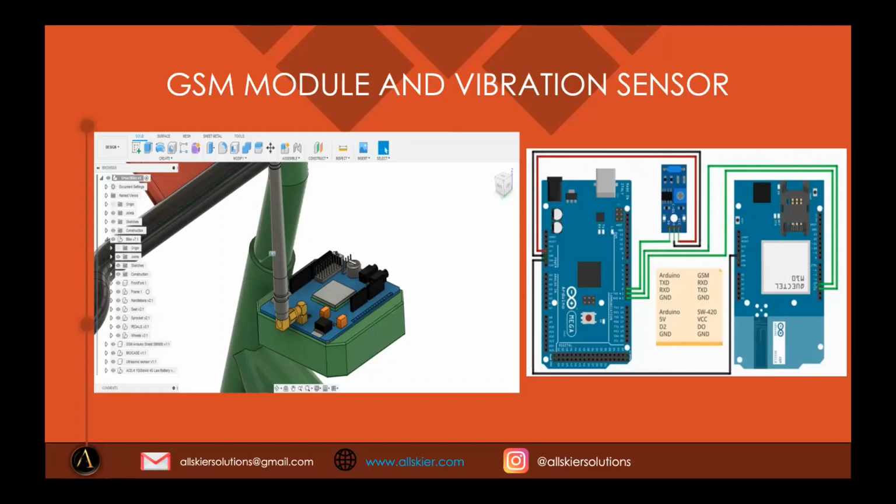Well, the microcontroller unit has an inbuilt op-amp, and it is able to amplify the signal. Well, what is the point of this op-amp? It has a preset value. So whenever the signal exceeds the preset value, only then does it trigger an alarm. That totally eliminates the false alarms which can come through even the smallest vibrations. So you can preset the value to any value so that it doesn't give a false alarm.